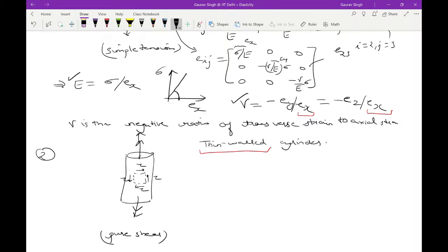The thin walled cylinder is subjected to a torsional loading, meaning twisting moments are applied, and then the state of stress in this situation for the same sort of this point in the center of this element over here, that can be represented by 0 tau 0, tau 0 0, and nothing in the z part.